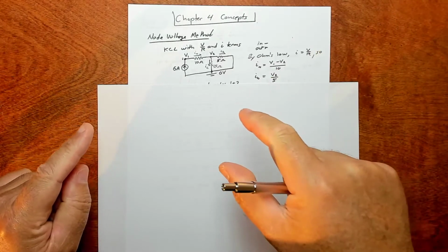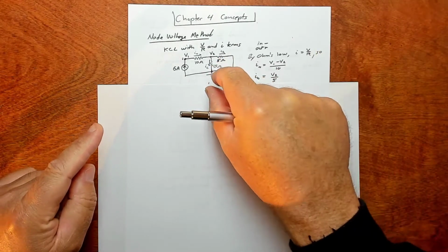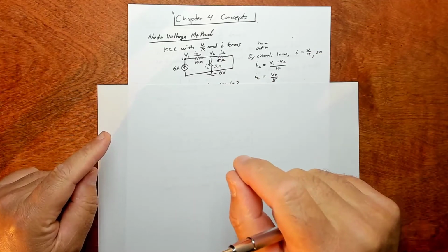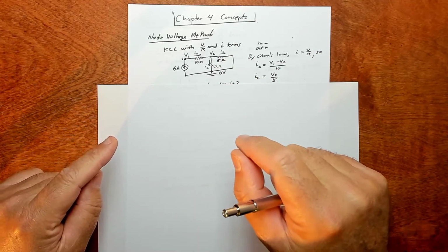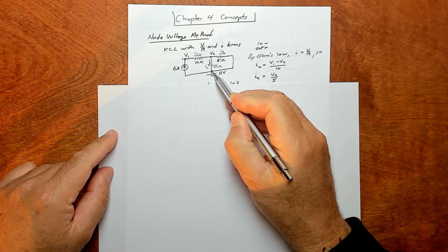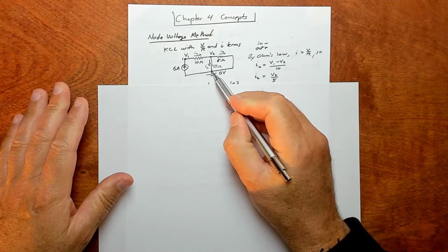And what you would do is you would take the black wire and connect it to ground. You'd connect it to what's being used as the ground for that device. So you'd hook it up down here. This is the ground. For these circuits, the ground's always going to be at the bottom.